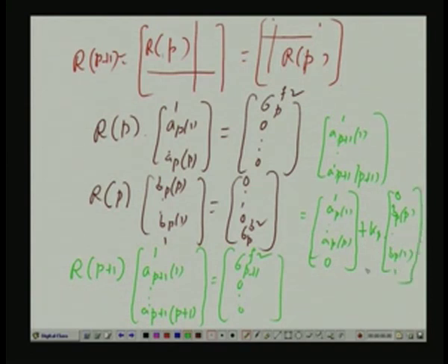My point is, I am just proposing, and let us verify that it is possible by a particular choice of k p. Can we write the p plus 1th order forward predictor, if we call it forward predictor, coefficients are called predictor coefficients, so forward predictor, as a linear combination of the pth order forward predictor and a 0, and a pth order backward predictor and a 0 on top? Can we do like this? Suppose we do. What is happening? You have to put then this on the left hand side. Can it satisfy an equation like this, where on the right hand side unknown is a positive quantity, but unknown quantity and all the terms are 0.